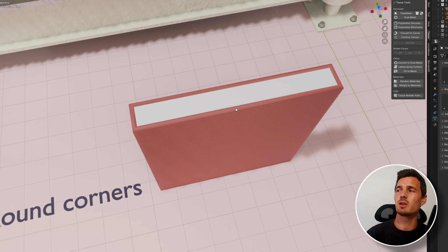So what it normally does, it starts to slow down as soon as it's going towards the corner, and then it goes that way. It starts to increase the speed again, it slows down again, and that means that you have more material deposition. Also, corners tend to curl. So corners have some extra material, they start to curl, and then layer by layer it starts to fail.